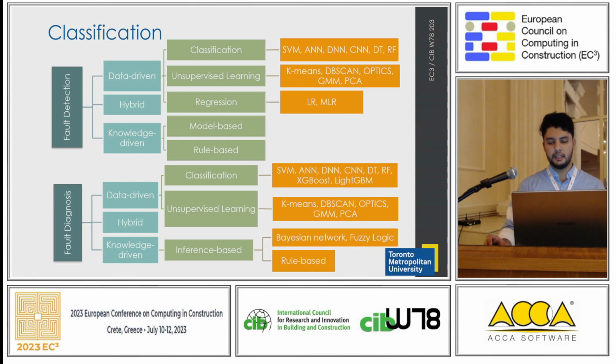On the other hand, we have knowledge-based methods. We can create a physical model of the asset to see what is the ideal operation of the system. And rule-based methods, it's like if the outside temperature is below 20 degrees, then the air conditioning compressor should not be running. And sometimes we prefer to tune the parameters of our model with process data. So this is going to be the hybrid method. And the main reason that we are interested in data-driven FDD methods is that they need little or no prior knowledge and have the potential to achieve high detection and diagnosis accuracy.